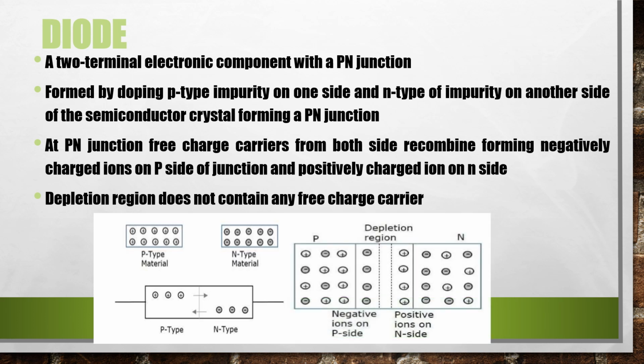Now look at this figure. As you can see here, depletion region is formed between p side and n side of this semiconductor diode. Further recombination of free charge carriers from both sides is now prevented because of the depletion voltage, which is generated due to charge carriers that are kept at a distance by depletion. It means here this depletion region acts like an insulation layer.